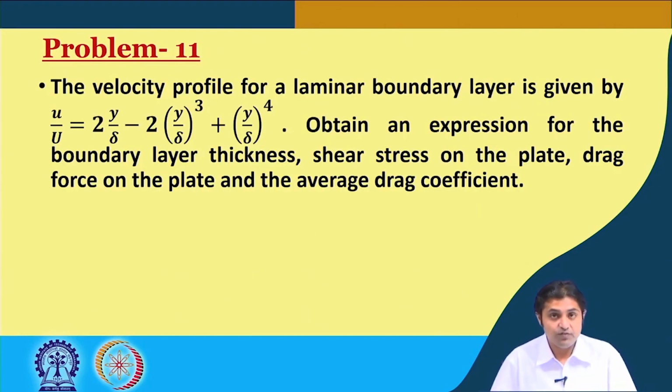So the velocity profile for laminar boundary layer is given, so it's not a cubic but it has one more term. Obtain an expression for boundary layer thickness, shear stress on plate, drag force on the plate, and the average drag coefficient. So this is a question where you have to find almost everything. All right.